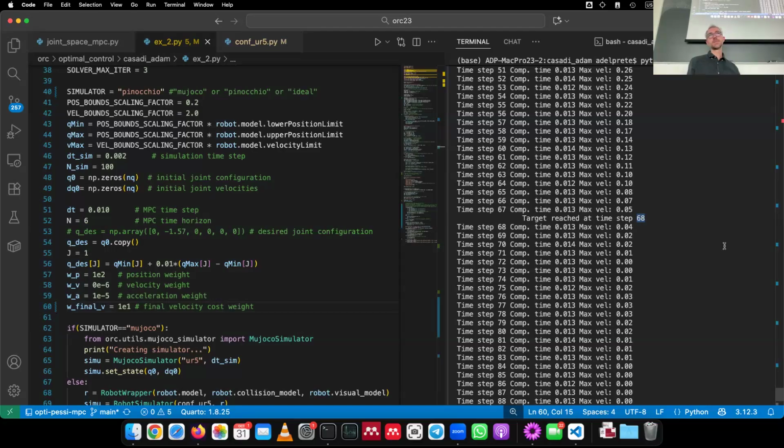And just for understanding completely, our terminal constraint now is that we want to be in the control-invariant set. Yeah, which is just zero velocities. How do we get to that zero velocity constraint? I get the idea of the control-invariant set, but how do we know that it's zero velocity? So there exist infinitely many control-invariant sets in general for any given system. Yeah, that was the one you like. This is the only one that's easy, so that you get it for free without doing any offline pre-computation.